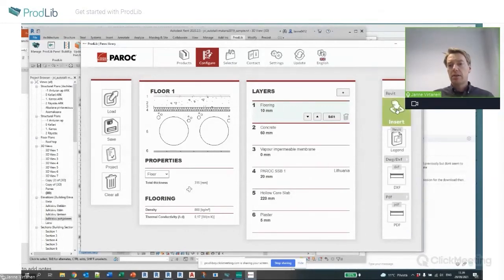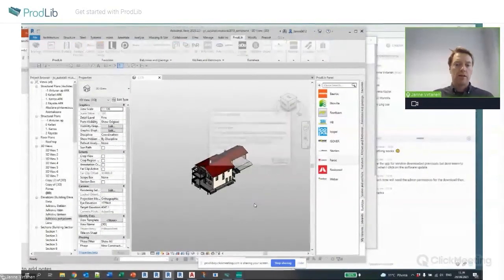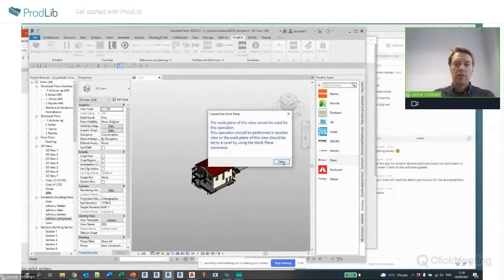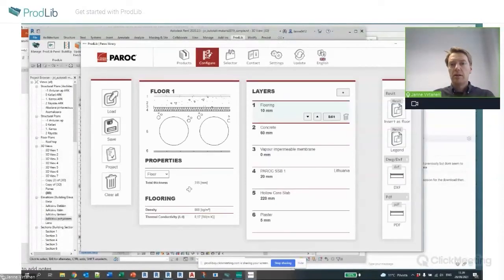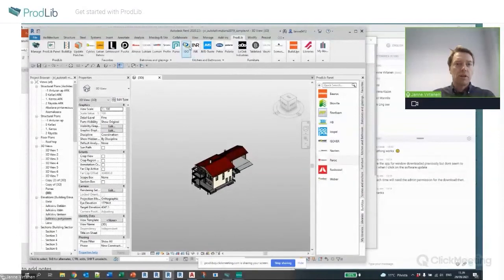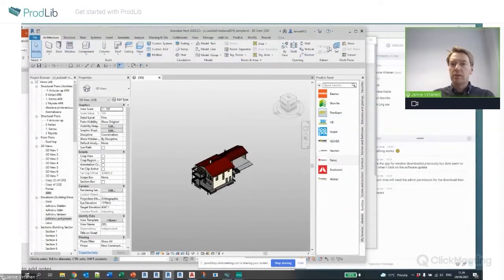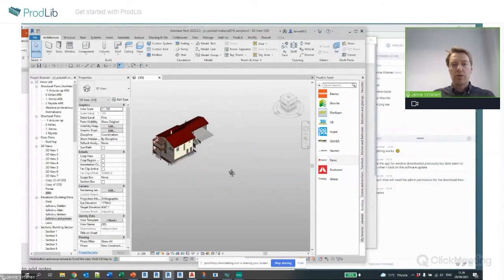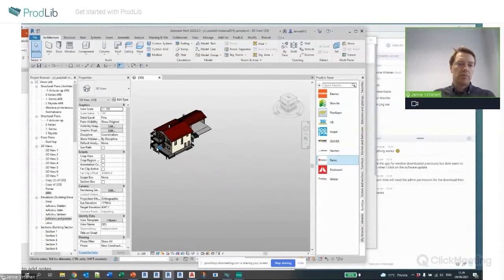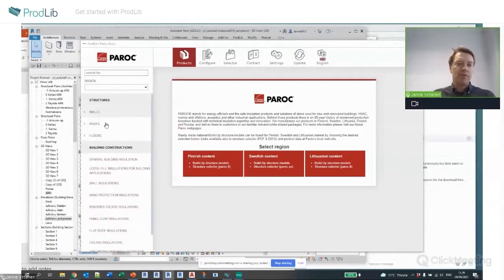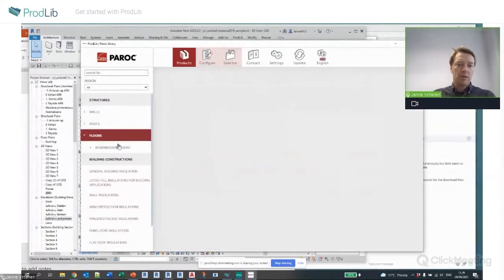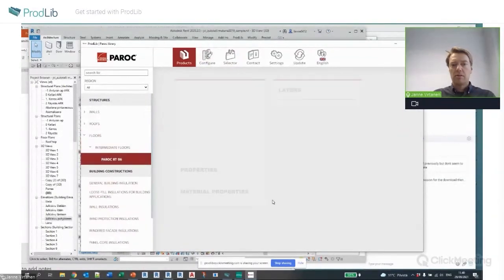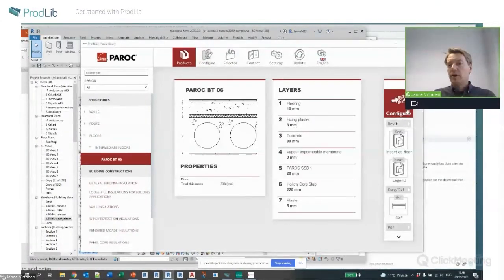And now in Revit, I can just start the floor command and it will create me, oh, sorry, I need to modify my work plane. Brilliant. I should have done this before, but that's easy. I have a sloping roof plane. It doesn't allow me to do a floor there. So let's go there. And of course, I didn't save my floor, but I'll just then pick one of these. This one that is available, and I'll select the insert as a floor.